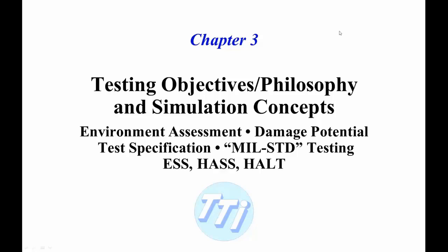What's going to break our specimen when we test it or in service? How do we specify tests? What are MIL standard testing? And then some side issues such as environmental stress screening, highly accelerated stress screening, and other associated testing strategies that you might use.